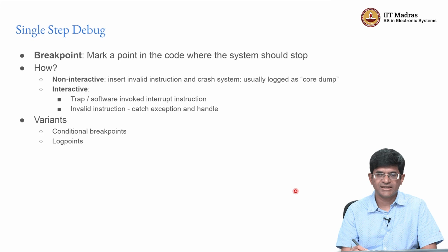hopefully some of you already noticed that there's a problem here, because the C code that we write is not exactly what is finally running on the processor, right? The C code gets converted, compiled into some kind of intermediate representation, and finally into machine language. So what is actually running on your processor is a set of machine language codes. So it is possible that a particular line in the C code that you wrote does not even exist or does not correspond to any final machine code in the actual system that is operational. But in most cases, it does correspond to code that exists in the final machine language.